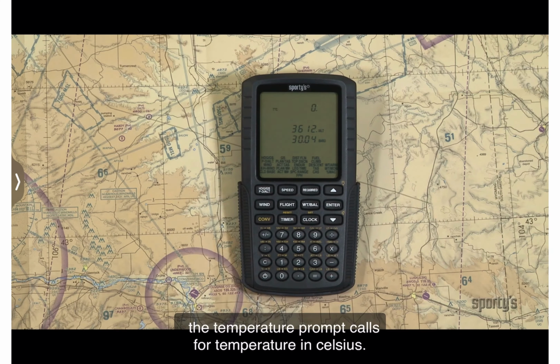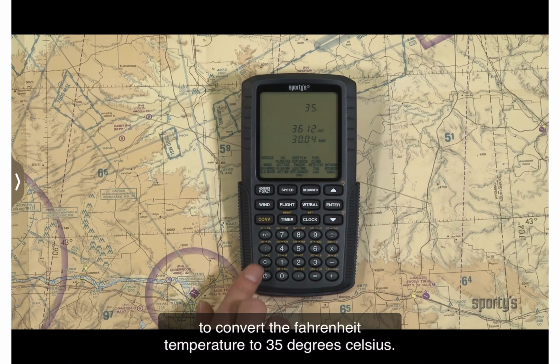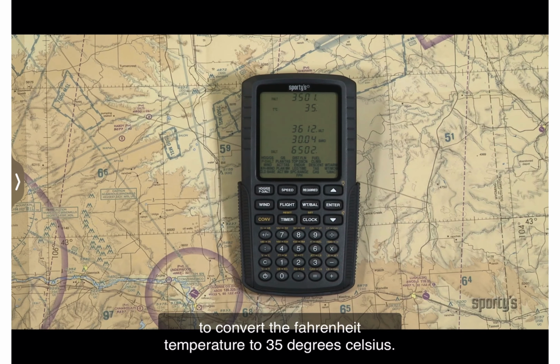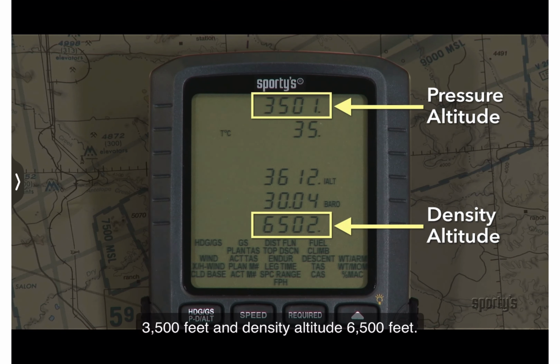The temperature prompt calls for temperature in Celsius. Enter 95 degrees and use the convert function to convert the Fahrenheit temperature to 35 degrees Celsius. After entering the temperature, the calculator shows pressure altitude of 3,500 feet and density altitude of 6,500 feet.